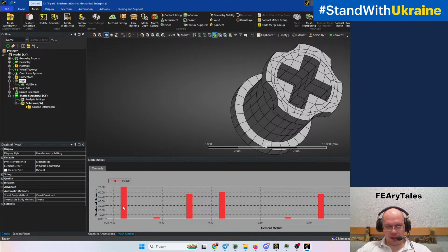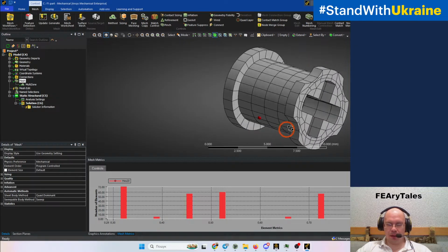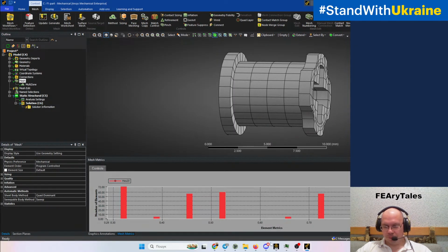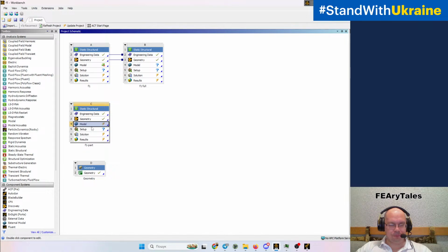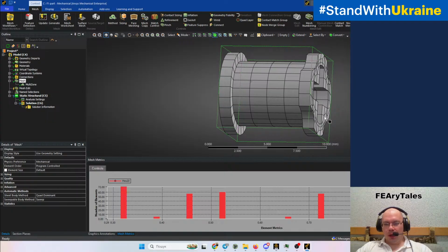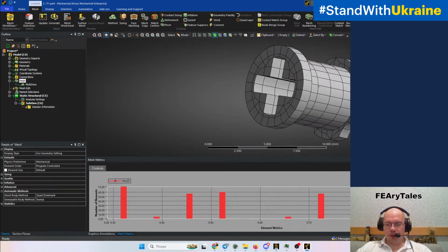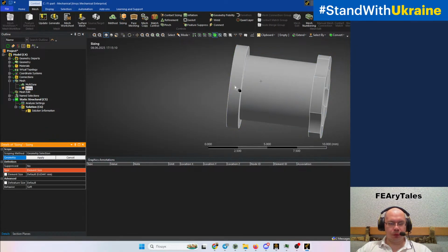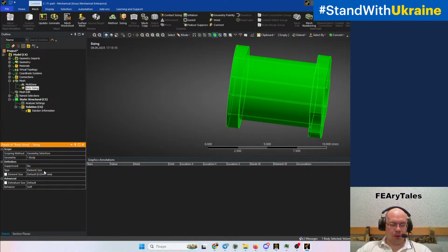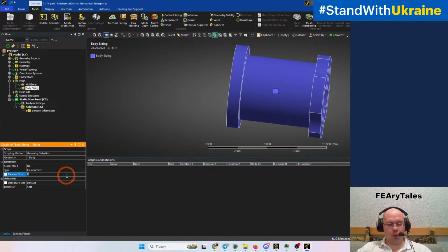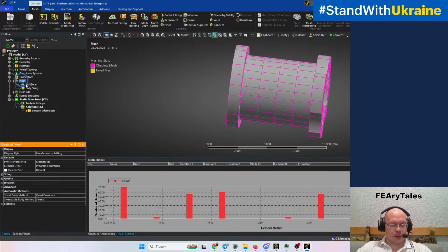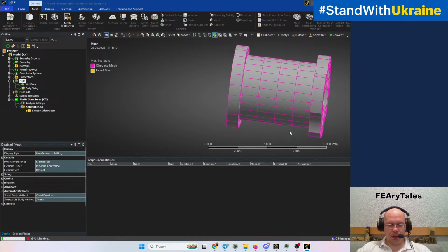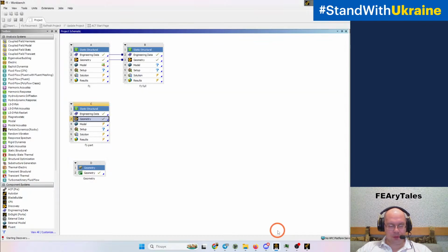Let's think, can we create a better mesh? So we will open the geometry. Okay, that's good. That multi-zone created maybe not perfect, but good enough. Also, we can produce the mesh settings like, for example, 1 millimeter with the size, and take a look while Discovery is opening.